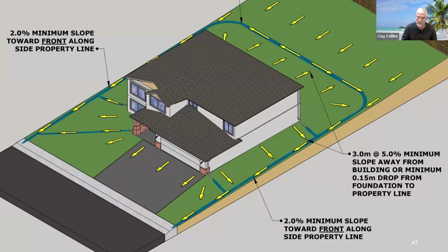That's a swale. That's a type A swale. And you see that it comes from the back fence down to the low part of the back swale. It comes from the house down to the back, the low spot of the back swale. And it runs around the house and it goes out to the street. That is the most common type of drainage that you're going to see, because it's all of those that are not on the corner. There's a different type of drainage pattern for those.